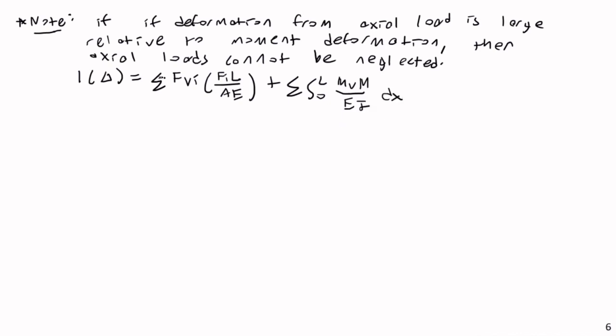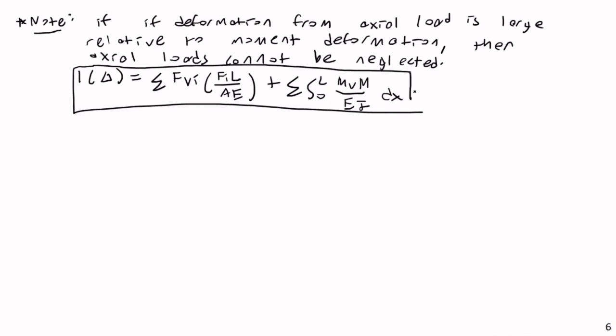So, like that example that you had comparing the origins, that's an example where you would take in actual force, right? So that's the 12 kips. I wouldn't necessarily say even that case, no, that wouldn't necessarily be a case where the deformation was large. Really, the question is, how do you know? Well, it's somewhat of a judgment call. One way to do it, you might look at the stress from bending versus the stress from axial force.